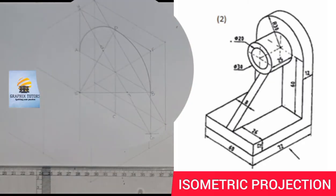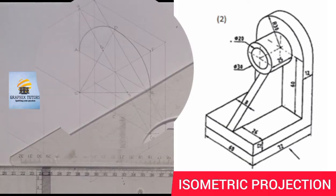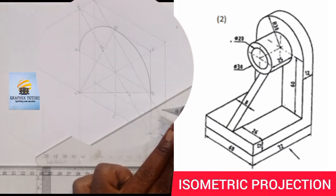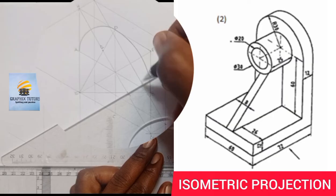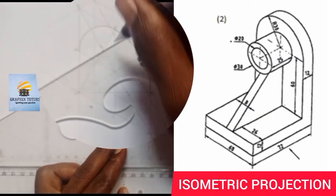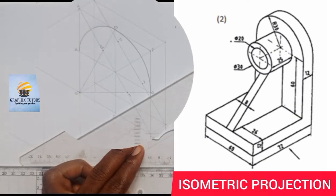So that is where I've gotten the first curve. Then I'll do the same thing, transfer those points. Now if I place my set square, this is the diagonal, this is the next diagonal for the back circle. So I'll transfer point 1 to come to this point, and I'll also transfer point 2 to come to this point. This is my new point 2 and point 1, right?